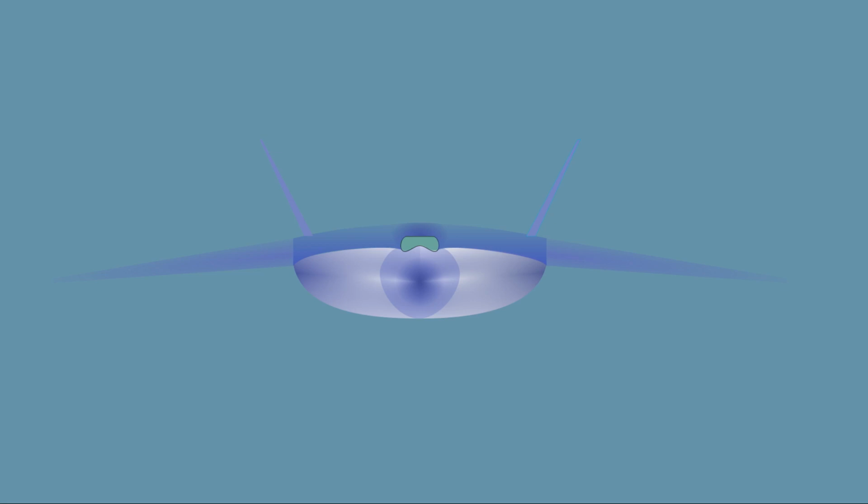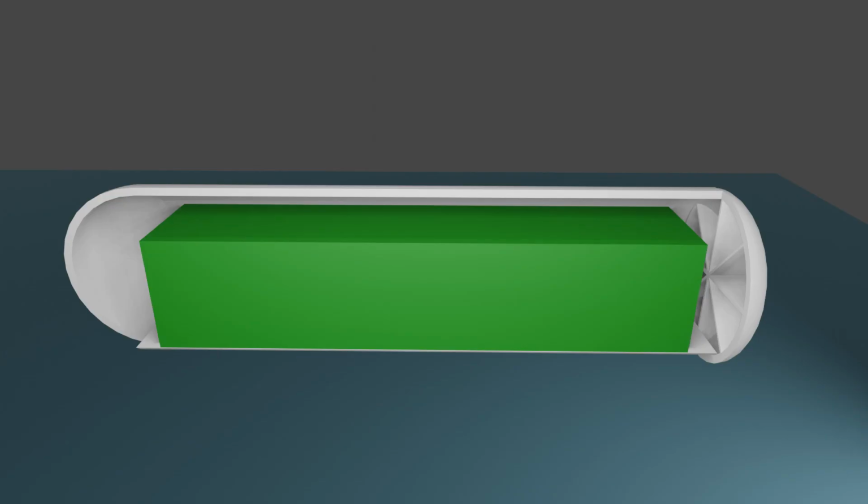If you had 150,000 pounds of cargo and 70,000 pounds of fuel, which is a relatively shorter range flight, each container would have 50,000 pounds. You have 2,500 cubic feet per container. The density of the cargo could be 20 pounds per cubic foot. Fresh water, for example, weighs 62.4 pounds per cubic foot. Most cargoes are relatively high density, and so that shouldn't be a problem.